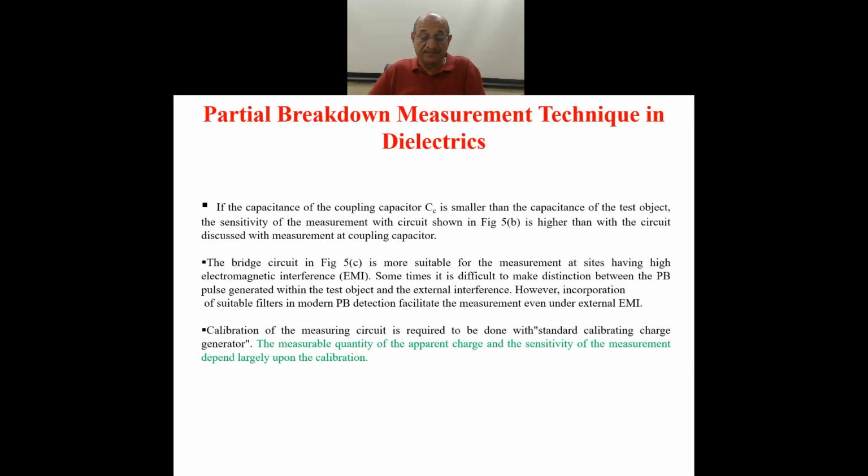Nowadays, however, with the incorporation of suitable filters, the PD detectors have been developed in such a way that they can distinguish the pulse from an external source and the pulse from the internal source or internal circuitry. Modern PD detectors facilitate measurement even under external EMI.